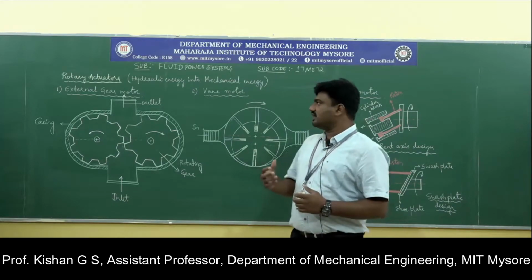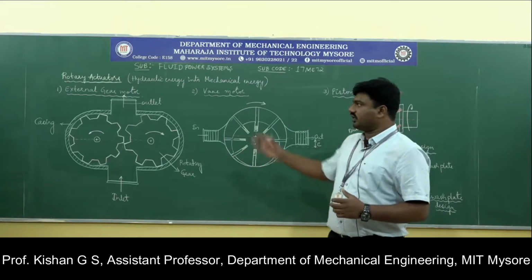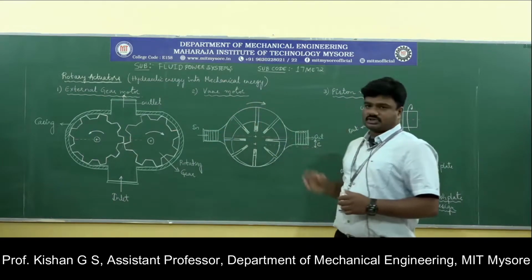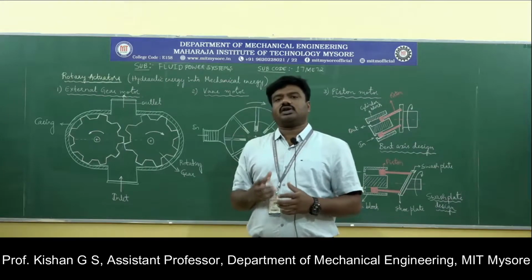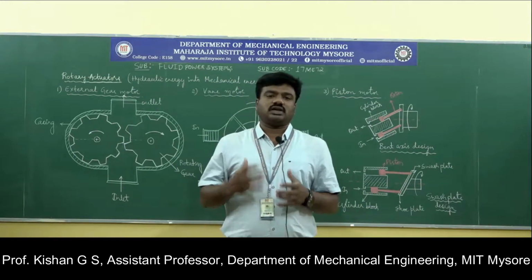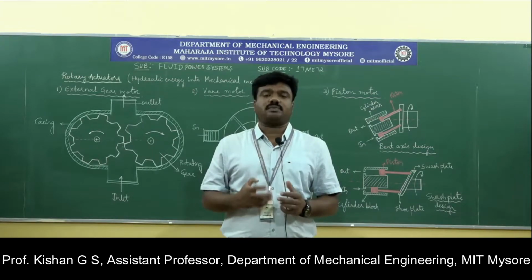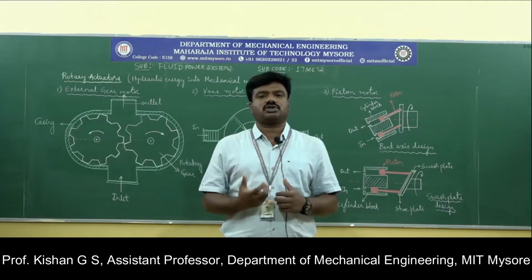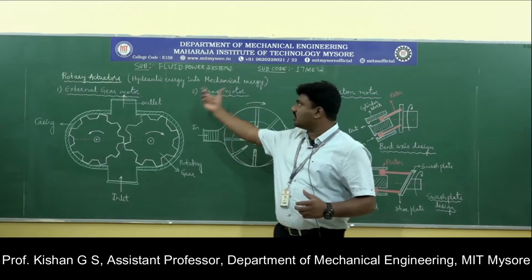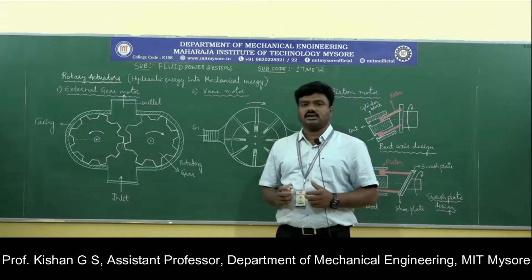Okay. So here we have three categories to be studied. One is the gear motor, another is the vane motor, and the last is the piston motor. Since you have already understood the construction of a hydraulic pump, the construction remains the same, except the working principle, which is inverse to that of the hydraulic pump. Please make a note of it: hydraulic energy is converted into mechanical energy.